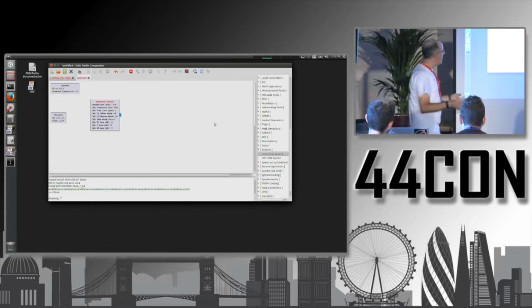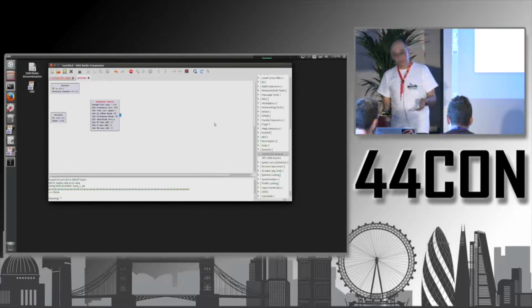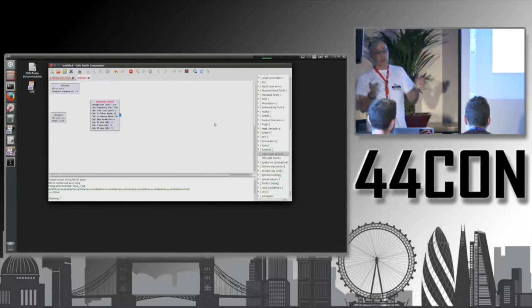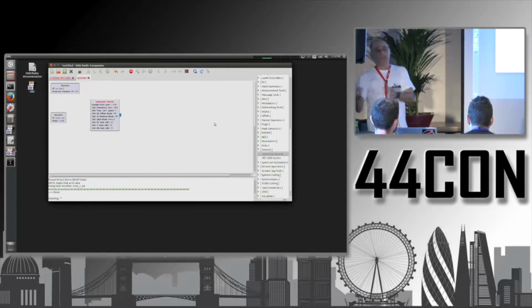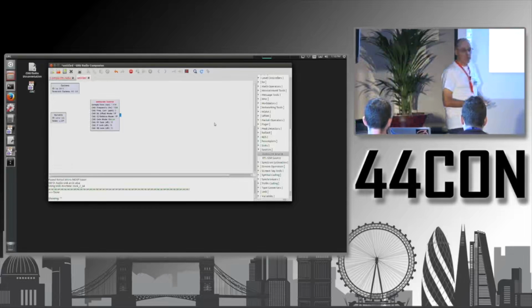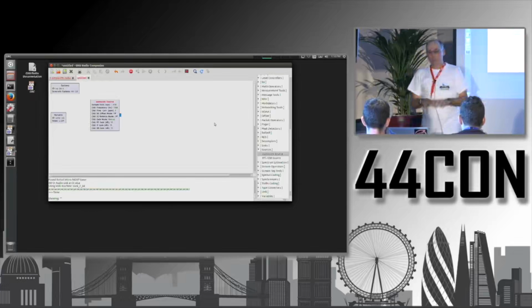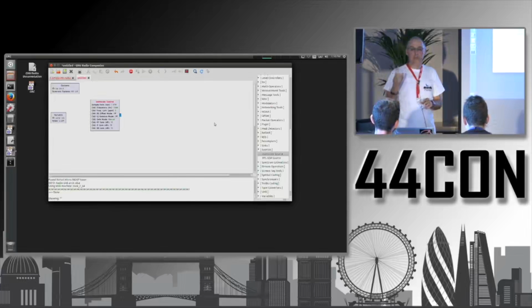Simply put, for example, if I have an audio wave of 1 kilohertz, then I would transmit on 100 megahertz plus 1 kilohertz. It's not as simple as that, but that's the gist of it. Okay. So, FM modulation, we encode a signal into the carrier wave by manipulating the frequency.